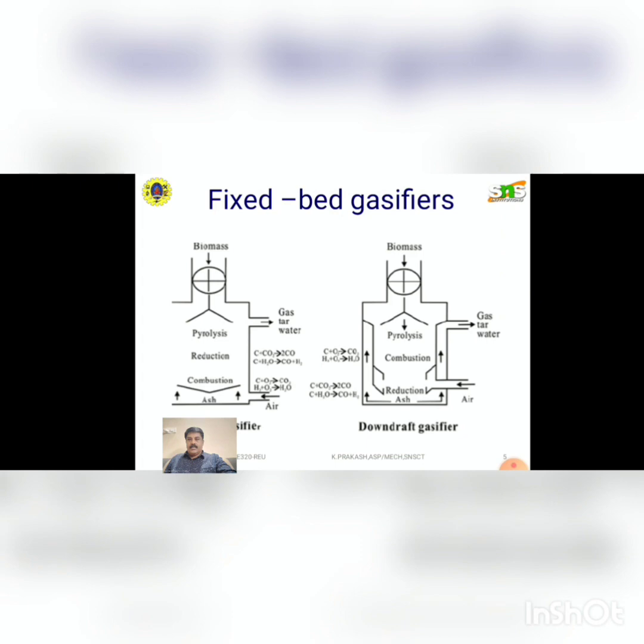The downdraft type is best suited for a variety of biomass. In this design, the raw products are forced to pass through a high temperature zone so that most of the unburned pyrolysis products, especially tars, can be cracked into gaseous hydrocarbons, thus producing a relatively clean gas.